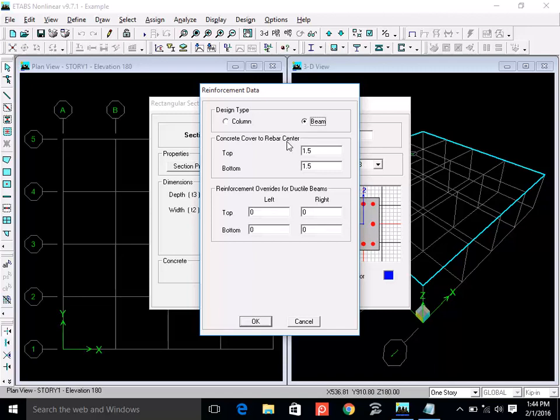Generally, the common sizes in Pakistan are number 3, number 4, number 6, and number 8. These 4 sizes are very common and easily available in the market. If you want a number 5 bar, you have to specially place an order, and then we manufacture number 5 bars.